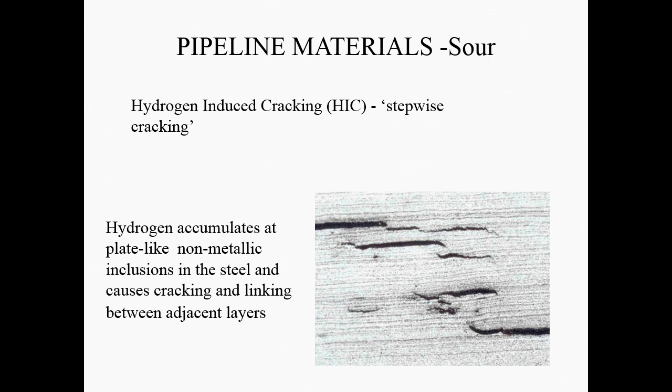And that enables you to jump from one level to another. So this crack is attracted to this crack, and this crack is attracted to this crack. You can argue it that way around. And that's why you can link individual crack layers, and then the cracks get longer and longer and longer, and eventually catastrophic failure can occur. So sometimes the cracks look a bit like a ladder or a set of steps. So you get a crack here, going up here, going up here, going up here, and running along. But if you look at the detail, the ends of the cracks tend to be a little bit bent over. So you don't want this to happen.